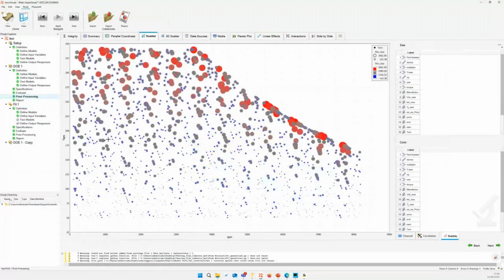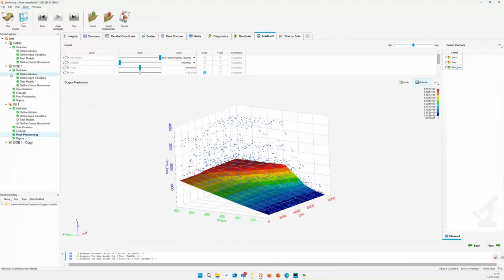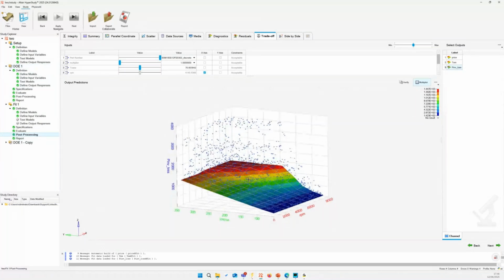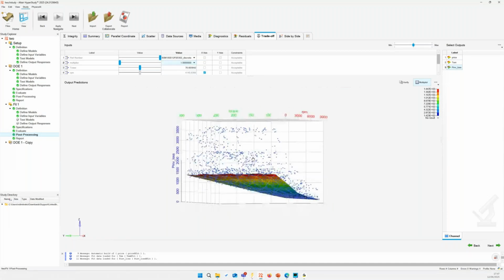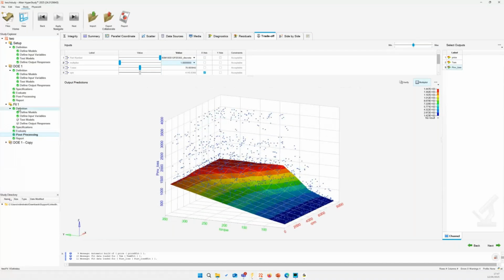So what I did here is I took all of the experiments of the design space exploration with the DOE. I ran a lot of operating points, not only for torque and speed, but I also changed the semiconductor from the two options you can see in this drop-down menu, changed the gate resistance multiplier to change the gate resistance, and also used a lot of different case temperatures for the cooling. And this is the design space. So the blue dots are the design space. And I can then create a fit model for this DOE.